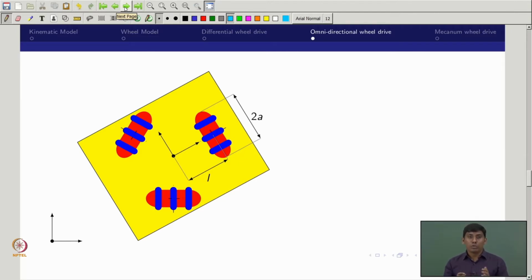Within the shop floor they do not want to move like a conventional vehicle, because the floor is smooth and engineered. So you can allow the lateral motion, but the same omnidirectional wheel or Mecanum wheel cannot be applied in a real environment. Why? The passive roller will not give the same performance on a non-smooth surface. That is why omnidirectional and Mecanum wheels are popular in warehouses. So now we will come back here.